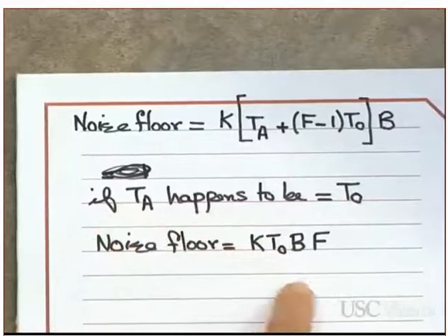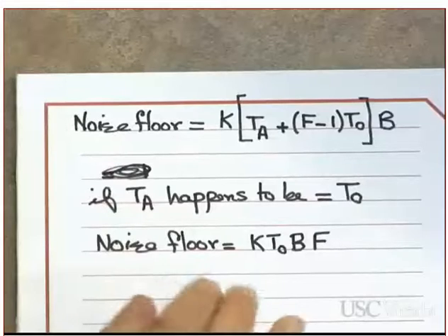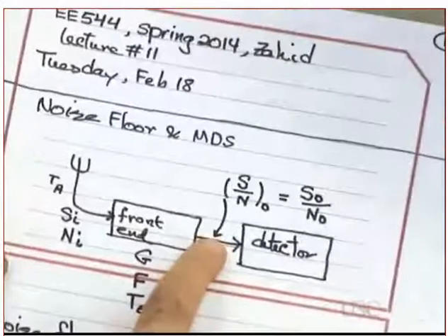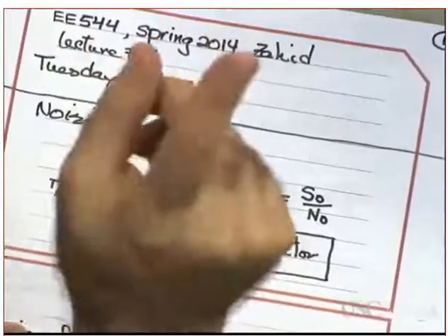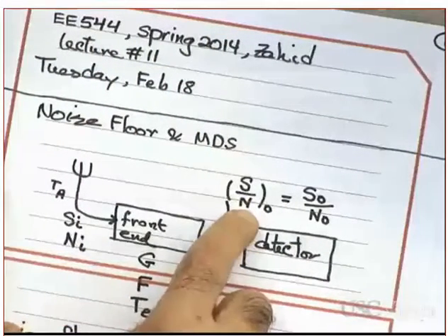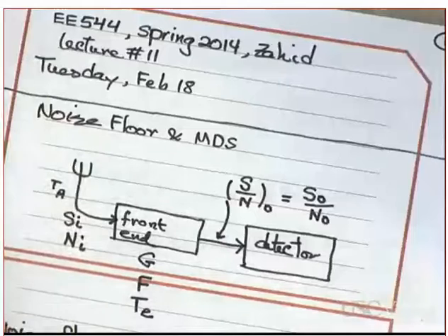Measuring this in the real world is easy. Why? Because all I need is the noise floor. Whereas the MDS is not straightforward. Why? Because the minimum signal to noise ratio depends on what type of modulation you are using. Are you following me or not?